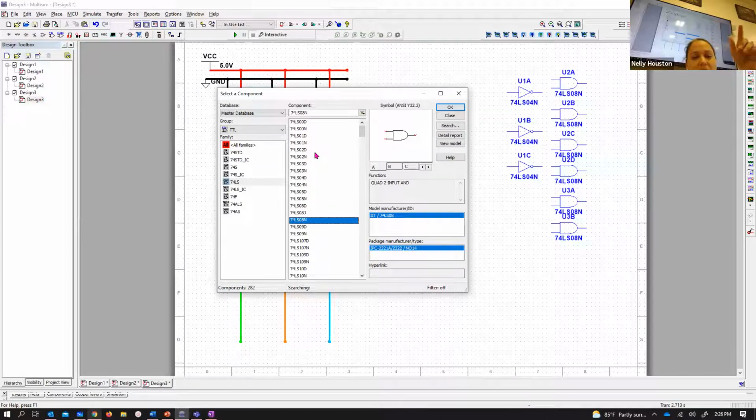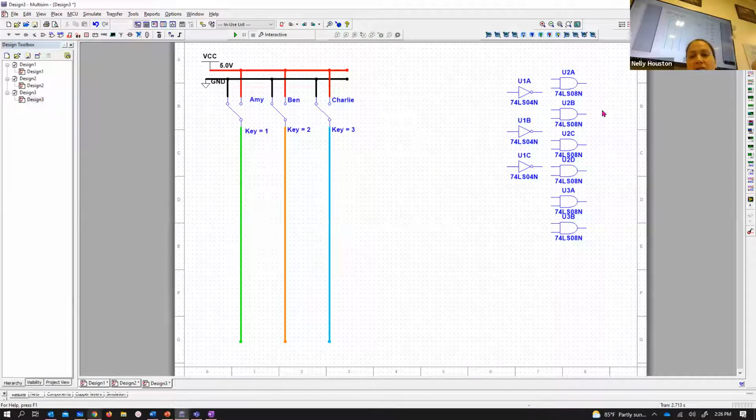Now watch this, the OR gate is 32, but it's not numerical. It's alphabetical, so the 100s come first, which is really weird. So you have to scroll down until you get to the 3s, which is after the 200s, and then that's the 32. Okay, and I need 2 of those. Okay, and close that. So they're all my components.